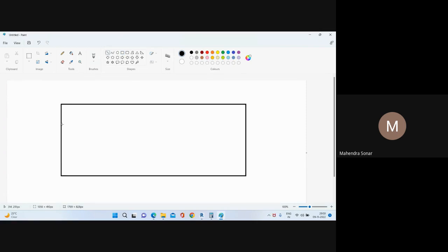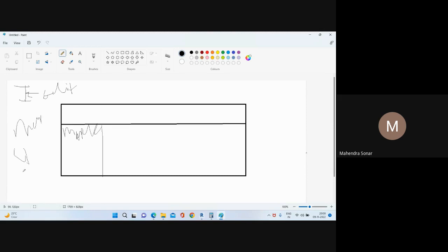So the title, first title is member schedule, then after that mark. Okay, so I will select here first mark. So if you remember, suppose this is my I section, so I have gone to this family in edit tab. Okay, and I have assigned the type mark as C1. Okay, so this C1, this type mark is the mark here.